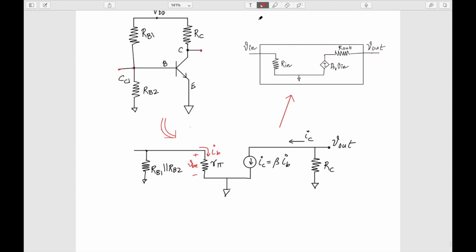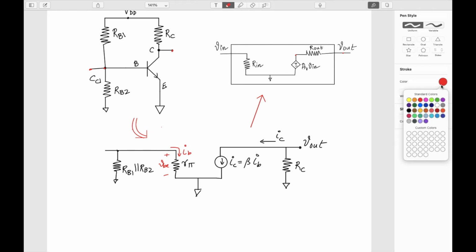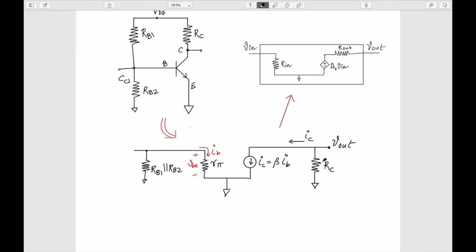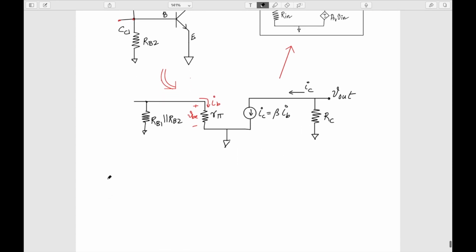Again, to find the gain, this AV, what we should do is apply a signal here, with RL equal to infinite. So that means this is my V in, and AV is basically V out by V in, given the condition that my RL is equal to infinite. This we have done multiple times, and in this case we know that this is minus IC RC by VT. In case you don't remember, please try to revise this part.